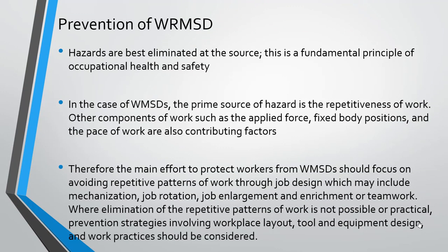The fundamental principle of occupational health and safety is to weed out hazards at the source. In case of work-related musculoskeletal disorders, the prime source of hazard is the repetitiveness of the work. Other components of work such as applied force, fixed body positions, and pace of work are also contributing factors. Therefore, the main effort to protect workers from work-related musculoskeletal disorders should focus on avoiding repetitive patterns of work through job design, which may include mechanization, job rotation, job enlargement and enrichment of teamwork.